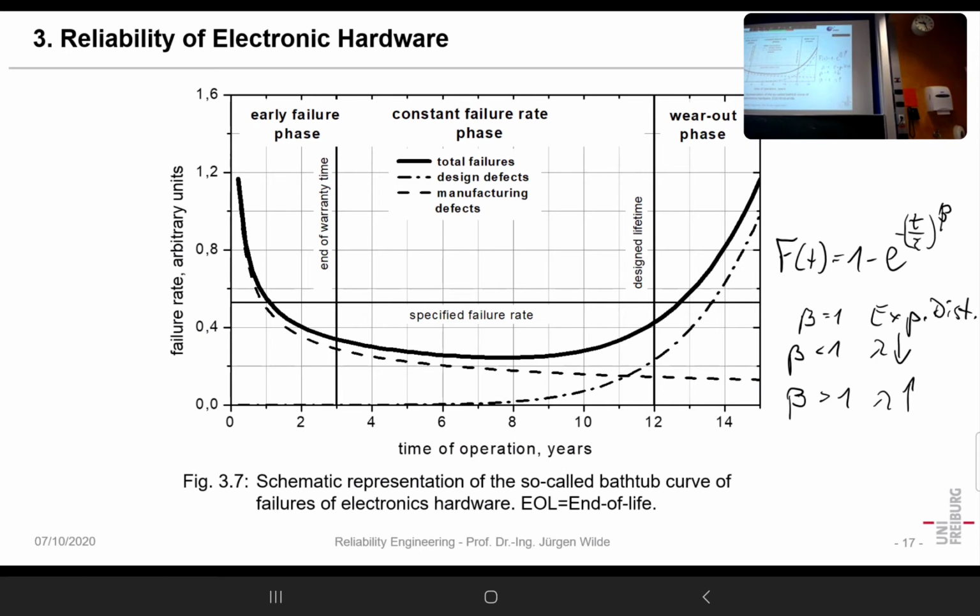When you look at any property of a part you produce, almost always the property is determined by some Gauss distribution. So you have a range of that property. If you take, let's say, a camshaft and you test it under always the same conditions, you can see sizes have certain tolerances with Gauss distribution, but also lifetimes will have such tolerances.